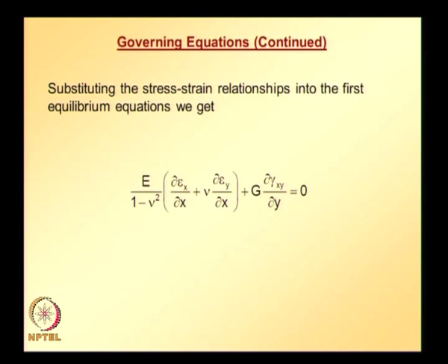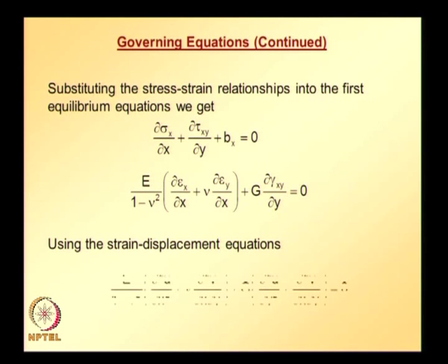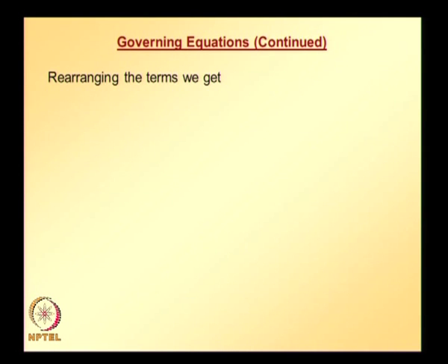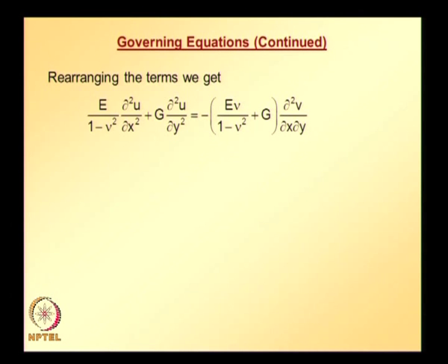And now this is how the equilibrium equation looks, neglecting body force, when it is expressed in terms of strains. And now when we write the strains in terms of displacements, it looks like this. And we can rearrange this equation into this form